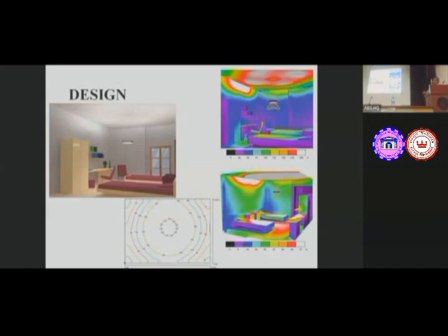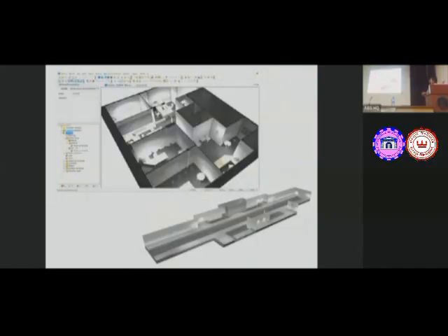Here we can see the isolux diagram or iso lines. On the line the light levels are the same on the working plane, and the working plane is not on the floor but at a certain distance above, normally on the tabletop. Normally on the tabletop this light level is measured. So it is an imaginary plane on the surface where you measure the light level. So this is for a single room design. Oh, just going back.